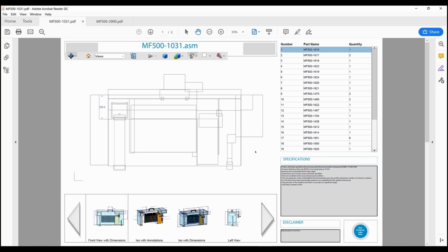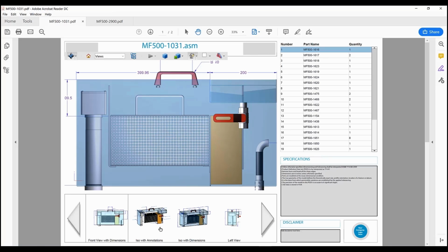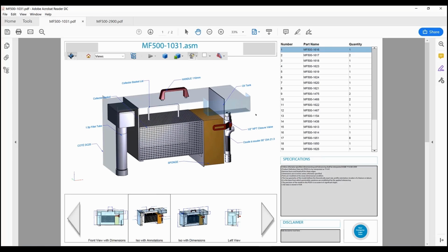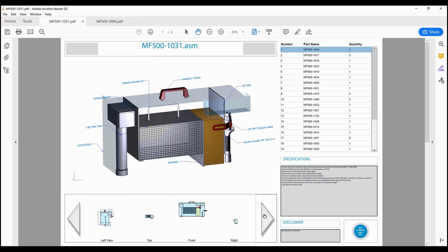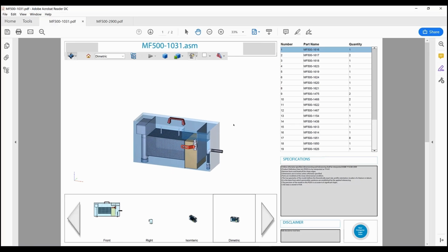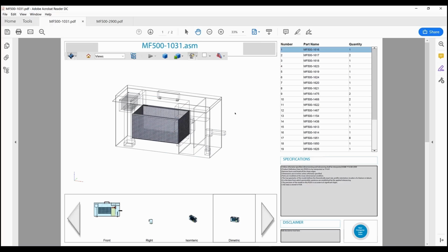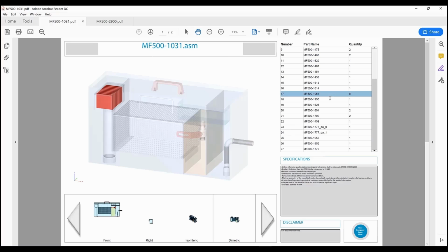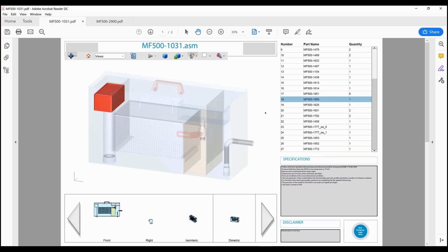Apart from standard elements like 3D view and view carousel, assembly 3D PDF documents can also contain a bill of materials. The bill of material is interactive. Let's take a look at how this bill of material enables interacting with the 3D view. By selecting a particular view, in this case isometric, the consumer of the document can either select a part in the graphic area and the relevant line item is highlighted in the bill of material, or vice versa.